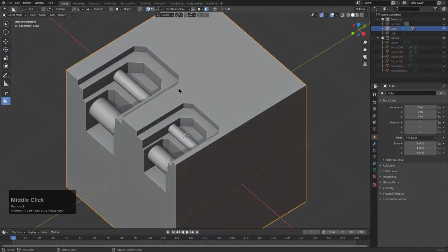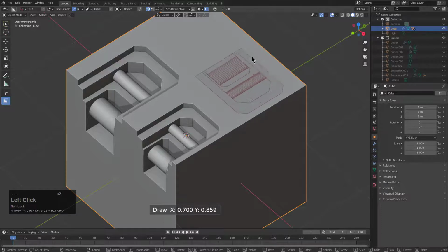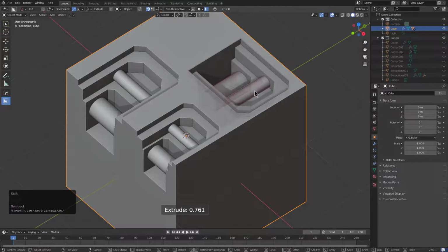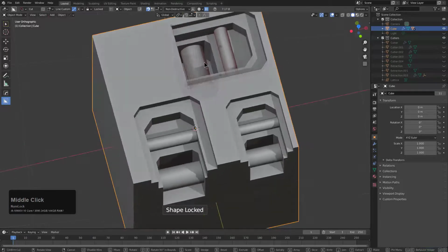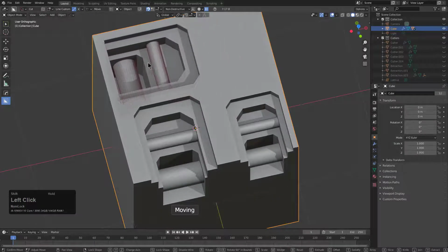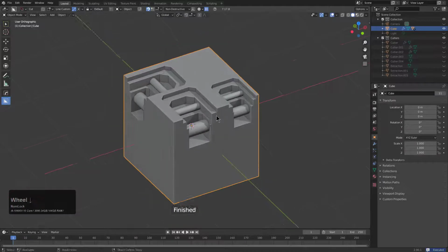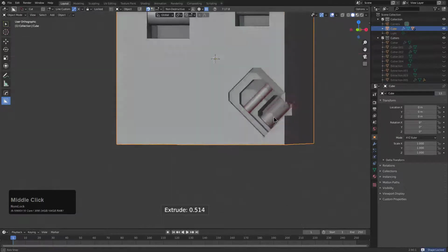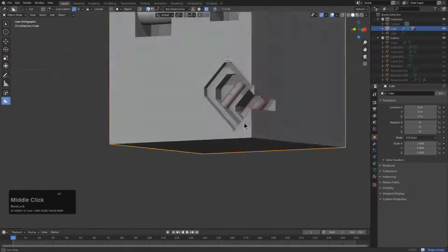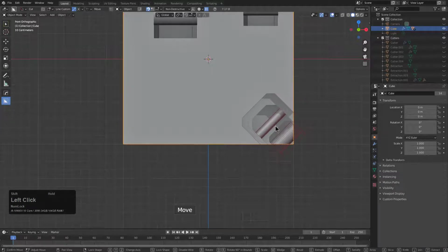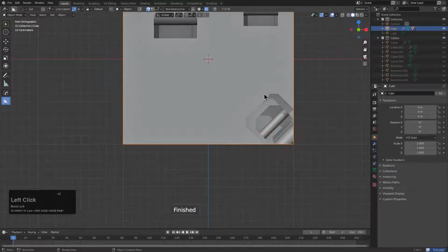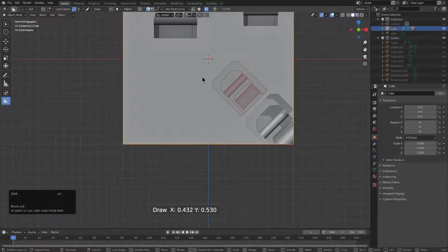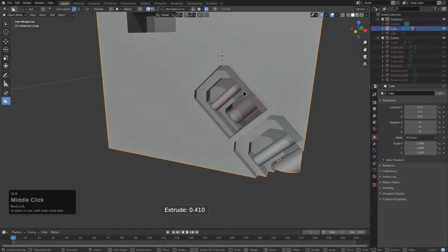And the interesting thing about custom is that if we were to turn on line custom, we can now draw a line, allowing us to draw this custom cutter in any direction that we want. Left click, right click in order to pause, or just press tab. And we can just move this shape around. Let's say that we wanted to actually draw this at an angle. No problem. And shift drag in order to get it proportionally accurate to the area that we originally took it from. And just like that, we can just begin imprinting this pattern just everywhere to our heart's desire.